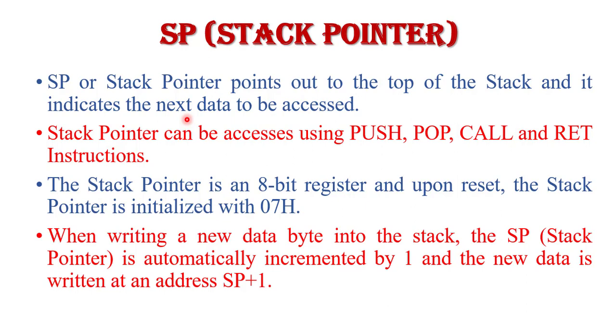The register used to access the stack is known as the stack pointer register. The stack pointer is also an 8-bit register. It is used to point to the top address of the stack and indicate the next data to be accessed.